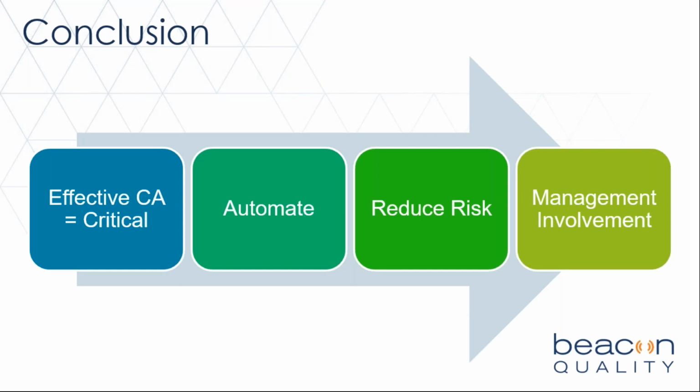Bring them on board, explain to them, and when you go to your management, speak in terms of dollars and cents. When you involve them, say this much cost, this much money, this is what is happening. If you put this corrective action in a certain way, if you have a poka-yoke, explain in terms of dollars and cents, and management will listen to you, because inspection is not a corrective action. Checking parts is not a corrective action. This is a non-value-added thing. Corrective action is to go to your process, fix your process, and then it should be a permanent corrective action.